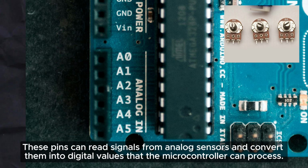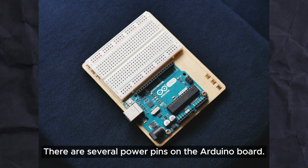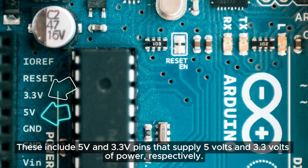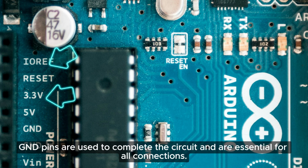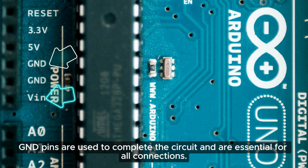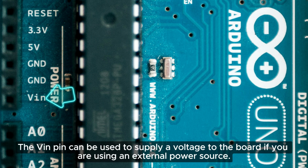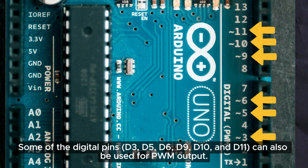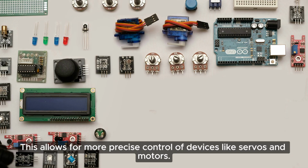There are several power pins on the Arduino board. These include 5V and 3.3V pins that supply 5 volts and 3.3 volts of power respectively. Ground pins are used to complete the circuits and are essential for all connections. The VIN pin can be used to supply a voltage to the board if you are using an external power source. Some of the digital pins, D3, D5, D6, D9, D10, and D11, can also be used for PWM output.